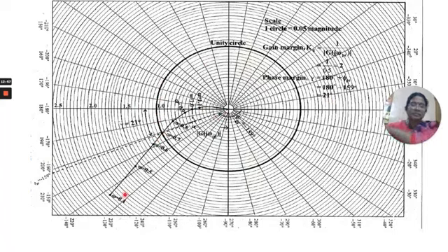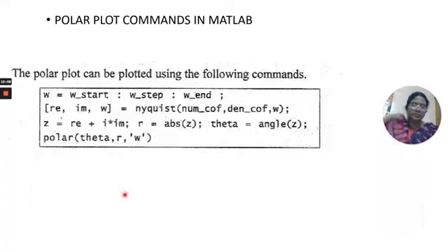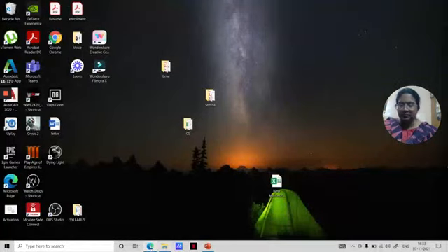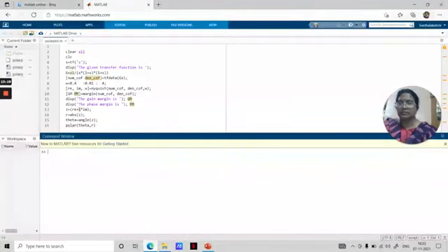Now we have to display our transfer function. So this line is given. The given transfer function is, then we have written our transfer function. Our transfer function is G(s) equal to 1 by s into (1 plus s) whole square. So I have written it like this. This transfer function is displayed in the command window. Then this command gives the numerator polynomial and denominator polynomial obtained from the transfer function.